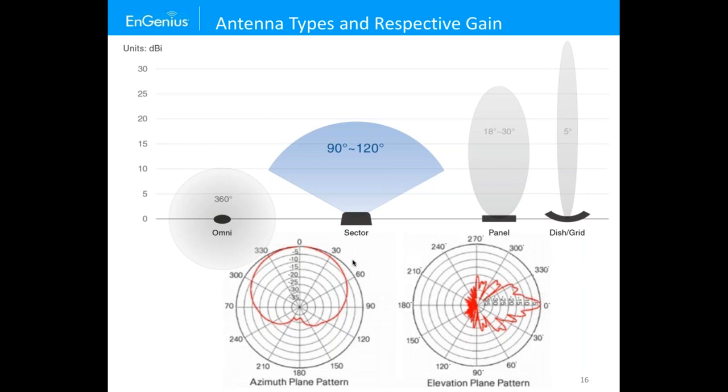It's just my ability to hear interference or focus my RF energy in a particular area that's going to be benefiting. So as you can see here, the antennas with the greater coverage are going to have less gain, less output power, less range. The one with smaller coverage is going to have greater output power, greater focusing. So EIRP will be higher. You'll get greater range from there.